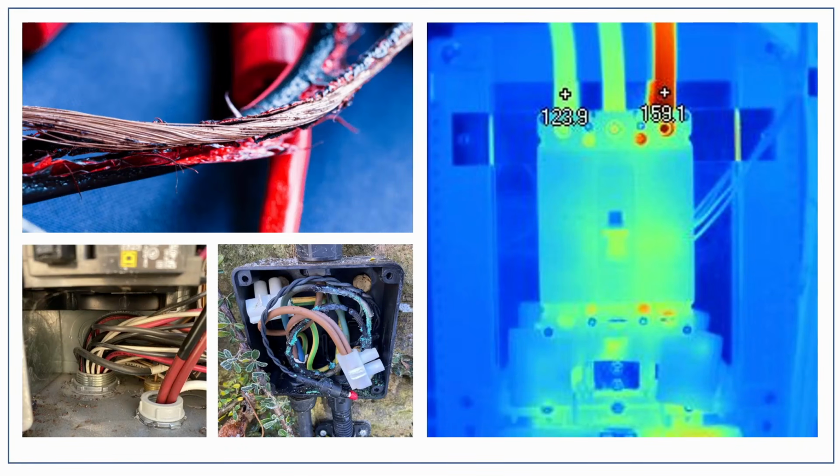Obviously, everybody knows the reasons why we're trying to determine the max ampacity. We want to make sure that the insulation of the conductors is not degraded, and we want to make sure that the copper has the ability to carry that current that we're drawing with each of our loads. Last thing we want is for the insulation to break down and have a line-to-line short or a line-to-ground short. Jamming a disgusting amount of conductors into the pipe and not allowing free air to dissipate that heat is not good practice whatsoever.